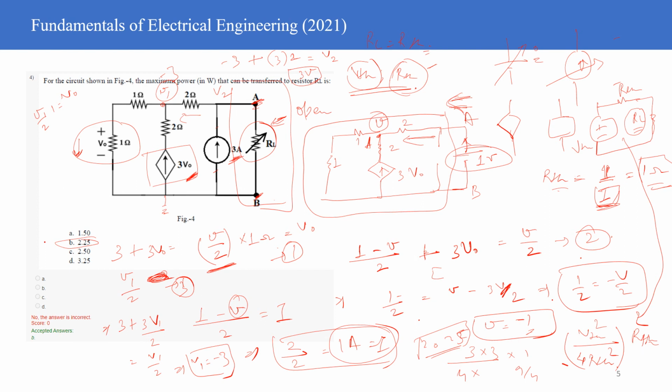The thing to take home from this solution is two things you need to remember. If you have a circuit with dependent voltage or current sources, you need to be cautious when figuring out the equivalent Thevenin's resistance. You can short all the independent voltage sources and open the independent current sources, but you have to leave the dependent voltage and current sources.